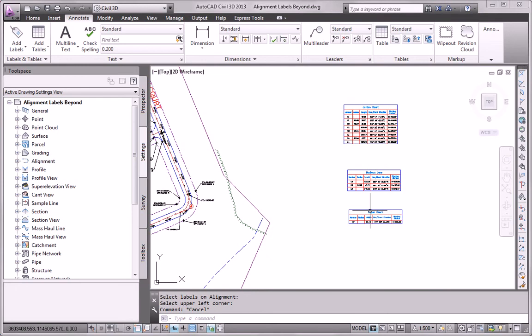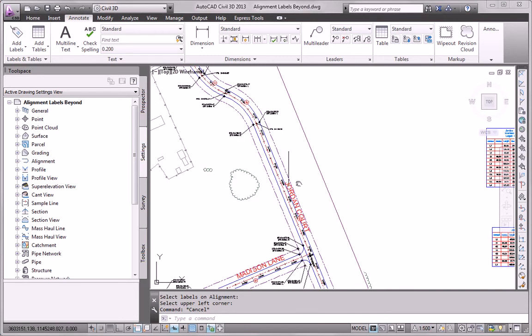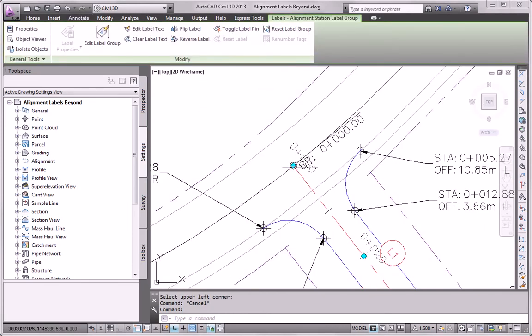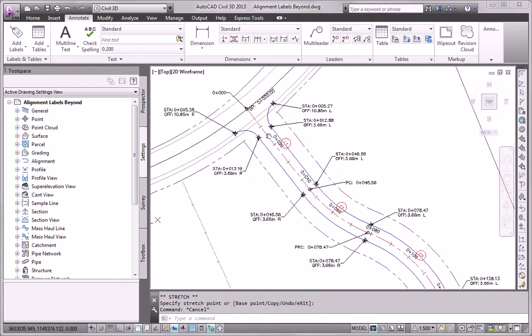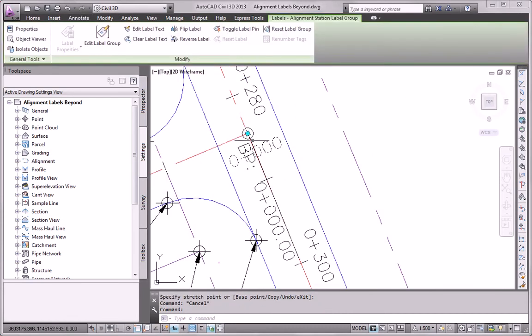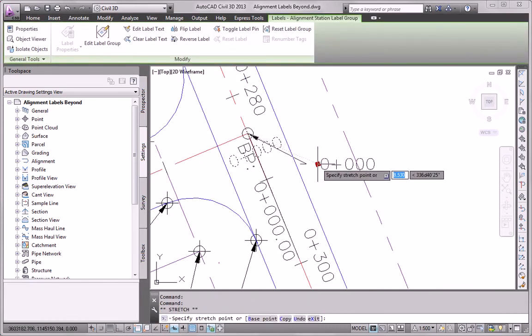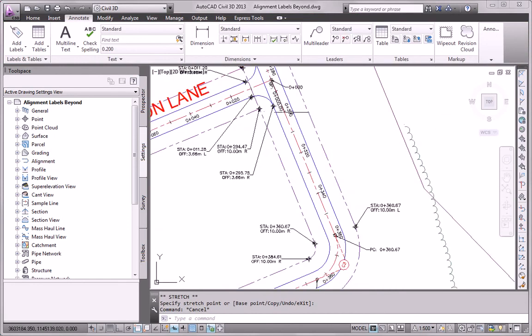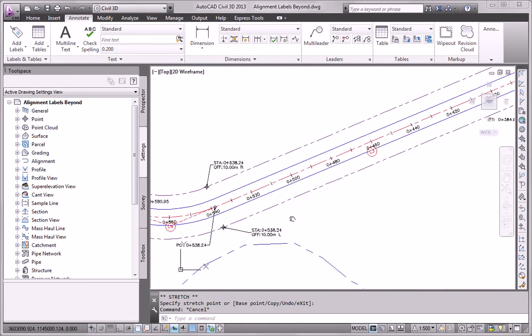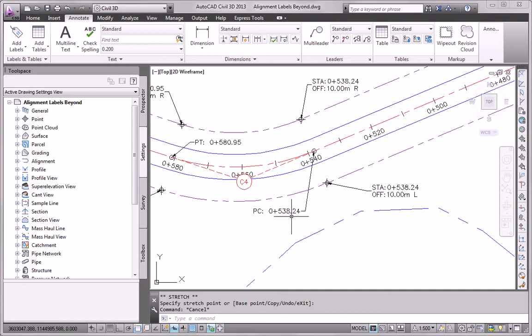Okay? And then step 5 says, in all cases, we want to reposition the labels so that there's no clashes with geometry or other labels. So just take a quick look at our layout here. We've got a couple of places where things are clashing, so we can use the handy drag state of the labels to clear out any clashes. Probably have one here. And everything else is looking pretty good. We've got a little bit of a clash here. Might look better if we move this